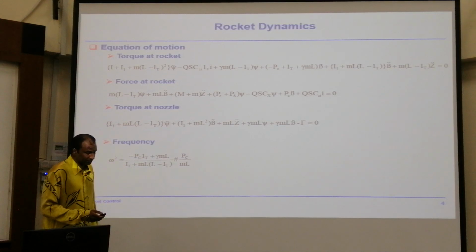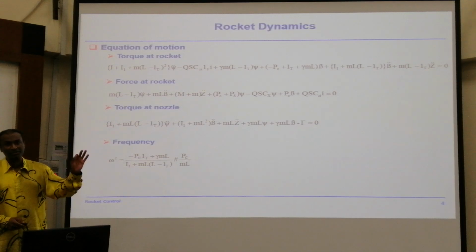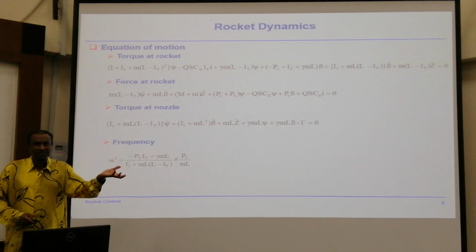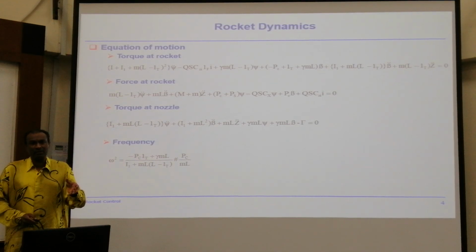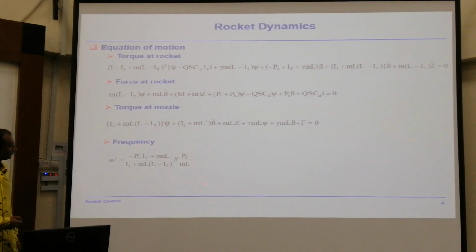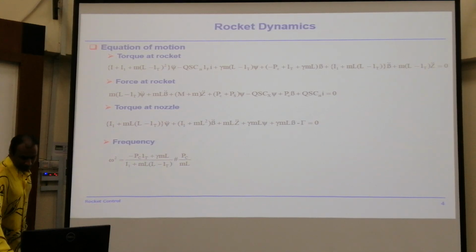that orbit. Now this frequency is also important because it also ensures all the other components in the rocket are safe. For example, you have the engine system, you have electronics, you have the gyroscope. All those, you want to ensure that all these are in a safe regime. So this is very, very important. So any launcher would actually provide you that frequency. And now you know how basically that frequency can be calculated. It comes from the actual dynamics of motion. Okay? So let's move forward.